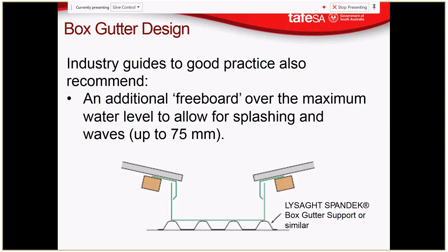What I have seen a lot in stormwater design, and it's allowed, is sumps. So I've seen it in ground. So you've got sumps in the ground, and then where you've got, I'm not sure if I drew this up previously in the class, we've got a street level up there, land slopes away, we've built our house with straight walls down here like that. And the height of our gutters is below the height of the street. Out back here we've got other houses and things like that. We can't send our stormwater that way. It has to go this way.